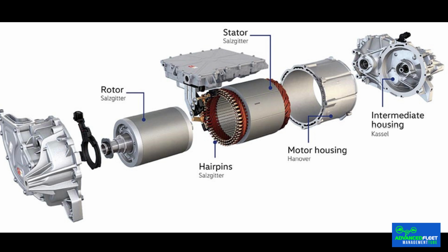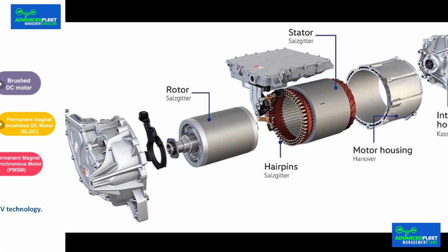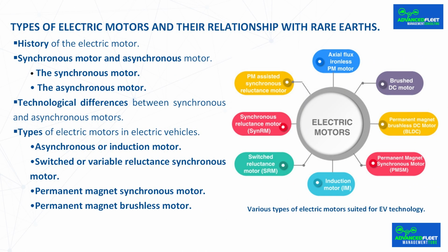However, it is precisely at this point where significant challenges arise. As soon as the rotor and stator poles are aligned, the motor will come to a standstill. For the rotor to maintain its rotation within the stator, it is imperative to reverse the polarity of the rotor magnets. This result is achieved by connecting the rotor coils to a rotating commutator. This device ensures the stability of the transverse direction of the magnetism as the rotor rotates. In this way, the magnetisms between the stator and rotor are never properly aligned, resulting in the rotor's continuous spinning.